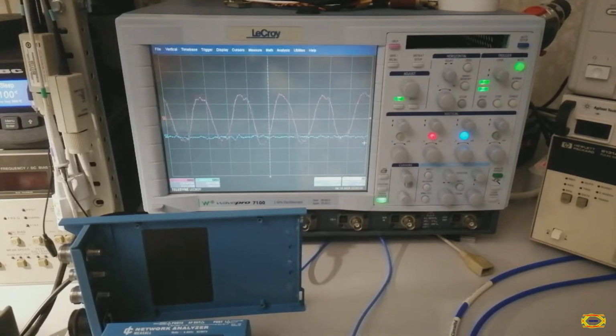I can show you this, but I have to repower the whole unit, so it's not so important for now. We have to figure it out. We have to understand what's happening in the PCB, in some block schematics. So let me show you the block scheme, and we can try to find some components on the PCB, probing it, and try to find the broken component.